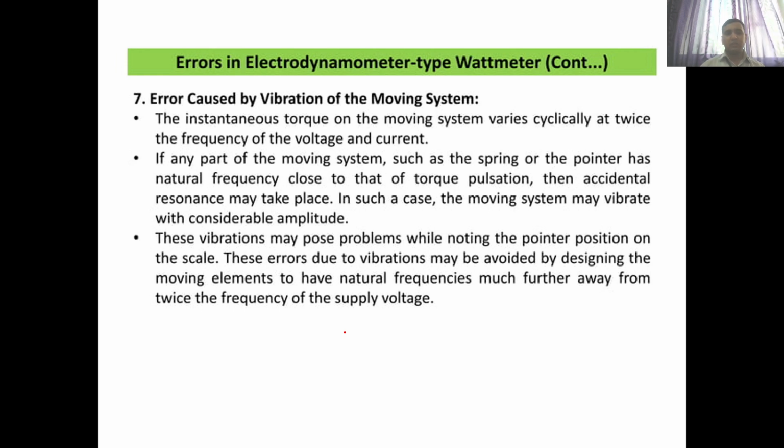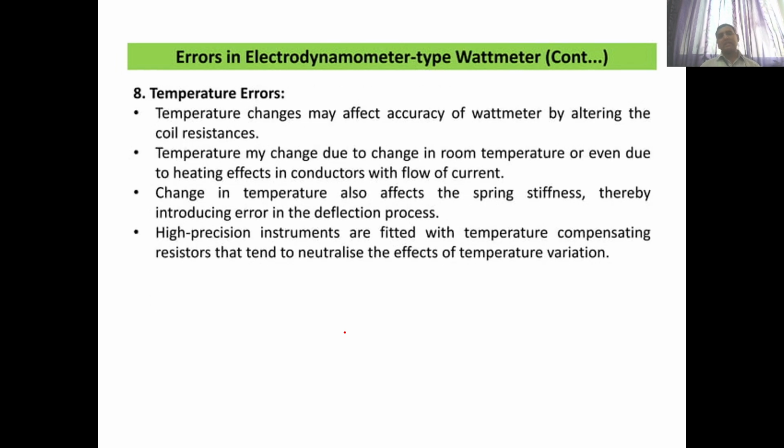And last is the temperature error, as the spring or other equipment having some resistance can be affected. The spring can become stiff, or the resistance values of the pressure coil and current coil can vary with temperature. So high precision instruments are used.